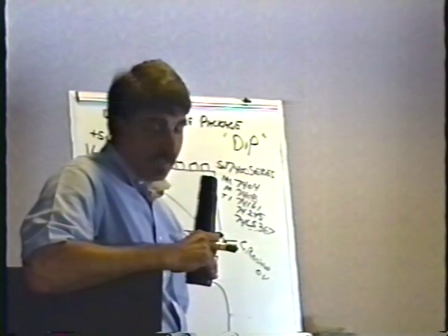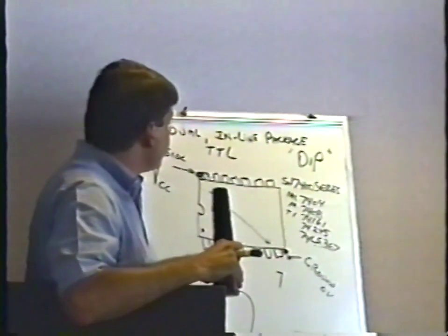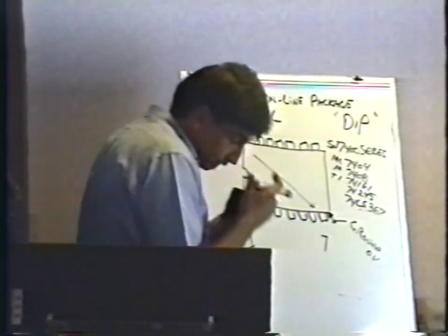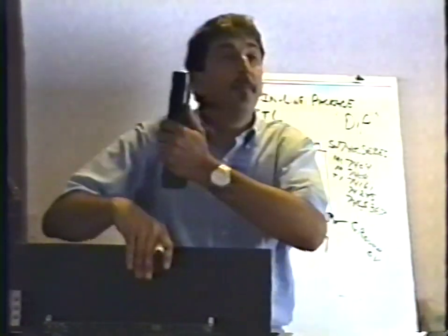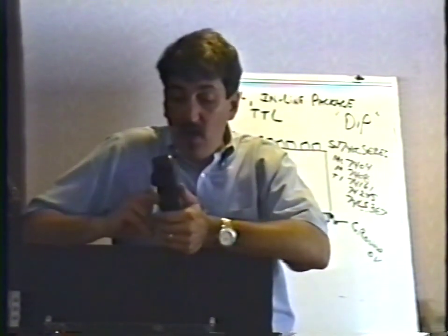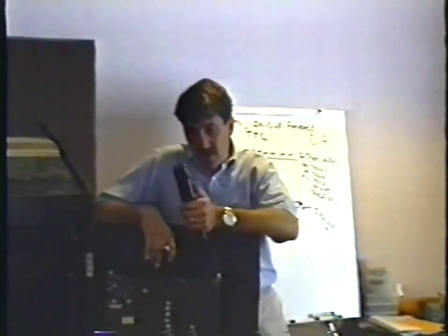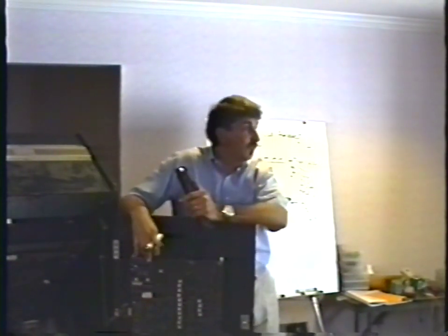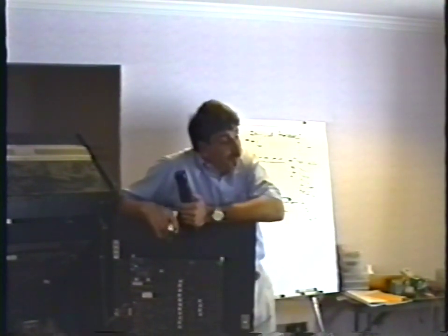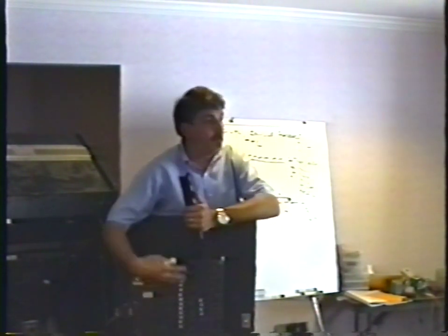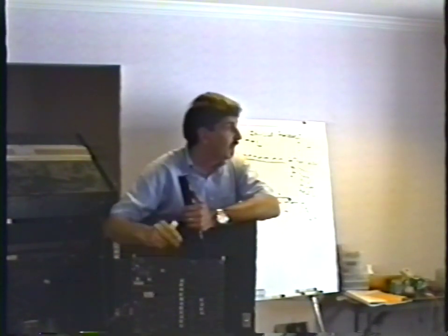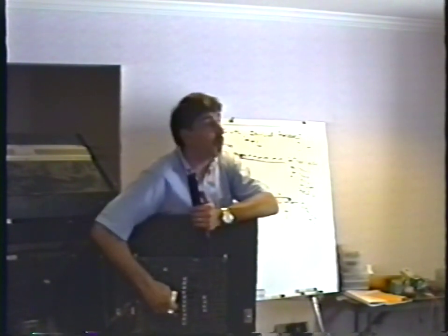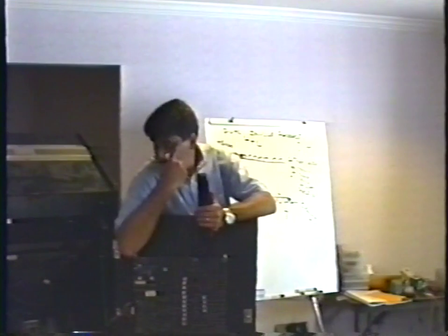Transistor transistor logic, TTL. So setting the 5 volts is really important. Let's say your game is doing all kinds of wacky things, like weird graphics on the screen, bits of garbage, it's freezing up, and you've tested the 5 volts on the board and adjusted it and it's perfect, and you still have a problem, you have a board failure. There's something wrong with your board. Don't give up. There's plenty of things that you can do, and I'll show you in just a second.